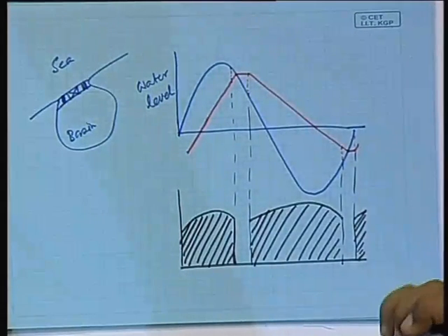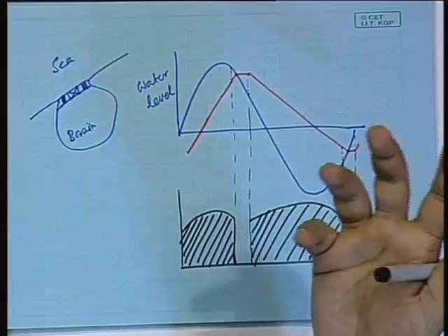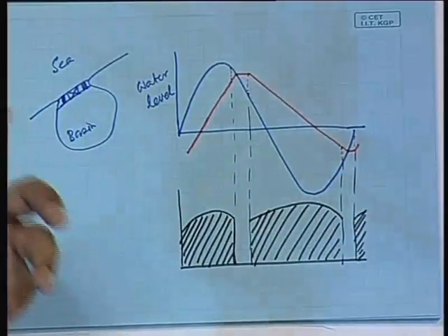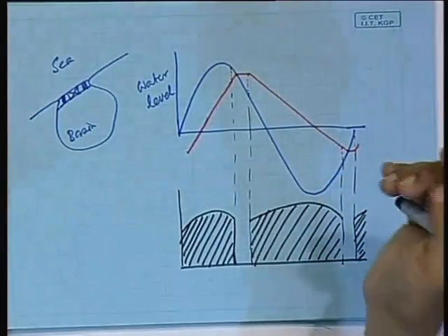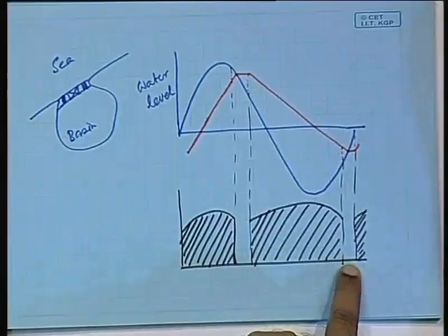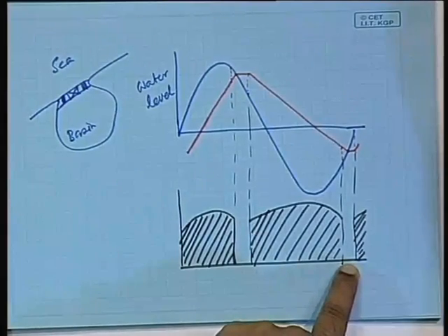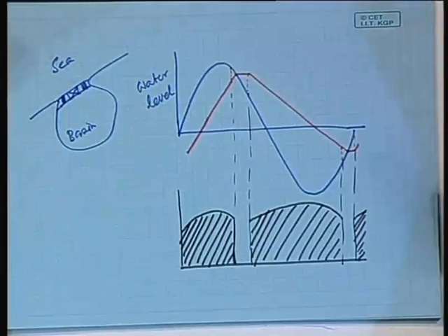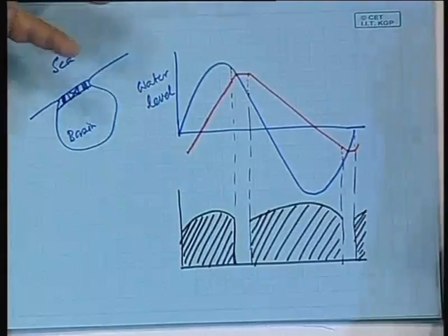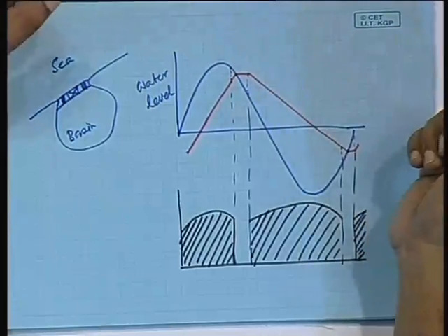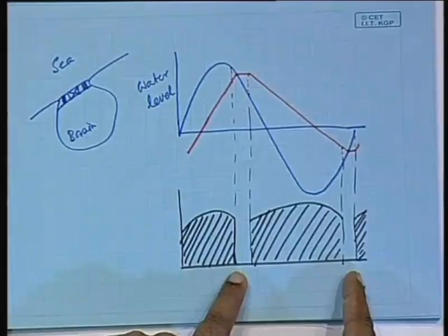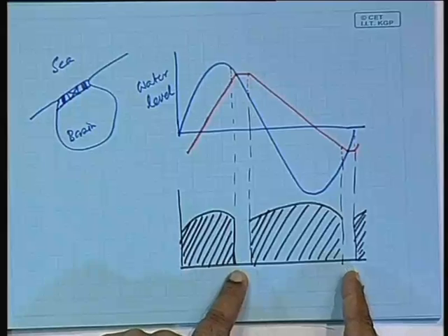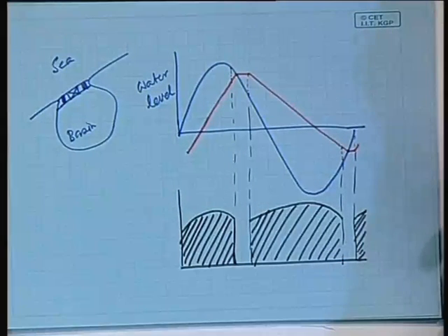In fact, the advantage of tidal power generation is that you have the power free. It is a renewable source of energy, but the disadvantage is that you have these times when you can generate no power. As a result, unless the power system is strong enough, that means it has excess capacity through other means, these times create problems, because suddenly there has to be load shedding because you are not generating so much power.